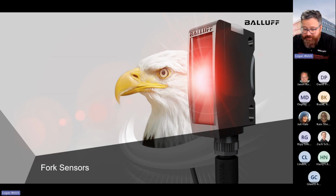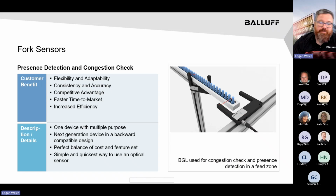Okay, really quick on fork sensors. I always like to talk about fork sensors for tricky applications, because sometimes the target itself isn't tricky, but the environment is, right? So say I had to read these bolts on a conveyor or a feeder. If I put a diffuse sensor there, I don't know. It's kind of tricky. It may or may not work. If it gets bumped at all, it's going to be shooting out into the air, or it's going to be shooting down on the rail. So I want to make sure it's aligned right at it.